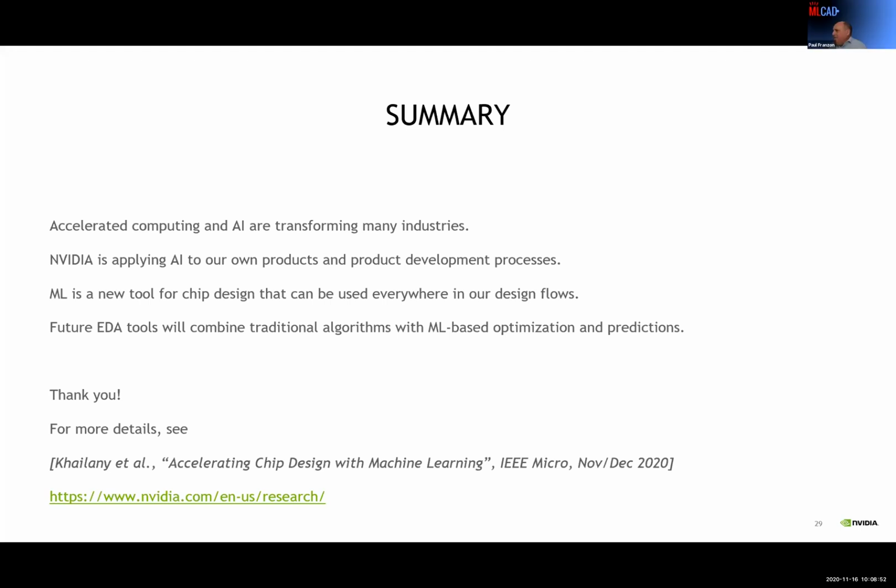How did you foresee defining rewards for place and route using reinforcement learning? It probably depends a little bit on the problem you're working on, but since you're asking about place and route, maybe you're talking about placing and routing of standard cells in a digital partition. You want it to be tied to the figures of merit you care about: wire length, an estimate of power, and some routability metrics. If you're not talking about final route, maybe the number of DRC violations, DFM type of things.